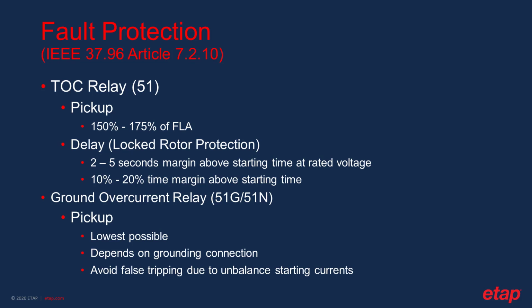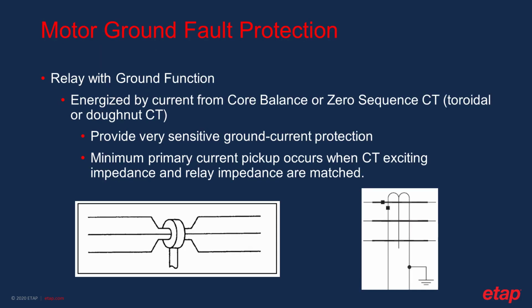If you have core balance CT or individual phase CT residually connected outside of the relay, in any case you need to set it up at minimum possible setting with minimum delay, but avoiding any false tripping due to these unbalanced currents. As we discussed for the ground function,